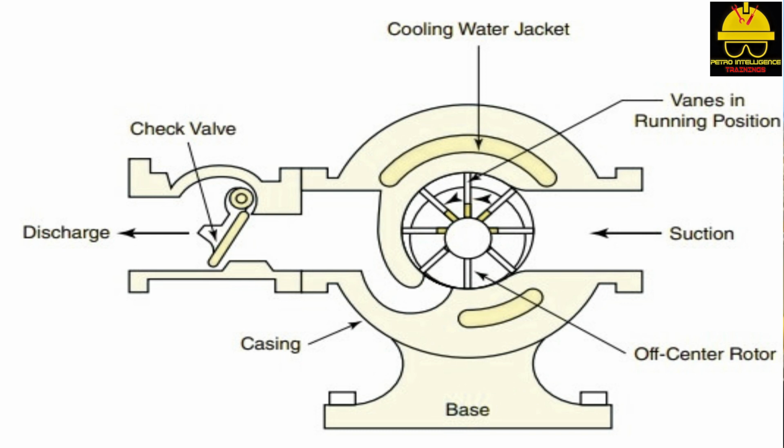The body of the compressor is fabricated from cast iron or steel. A set of cooling water jackets is fabricated into the initial design and tested for tightness. The rotor and shaft are made of high-strength alloy steel. The rotor is precision-made with slots around the entire rotor. The sliding vanes are composed of asbestos phenolic resin, metal, or high-temperature, durable metal.